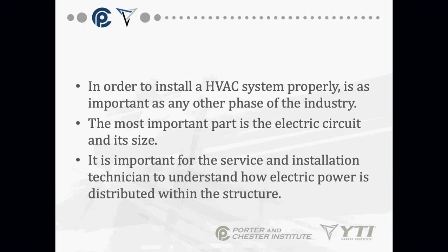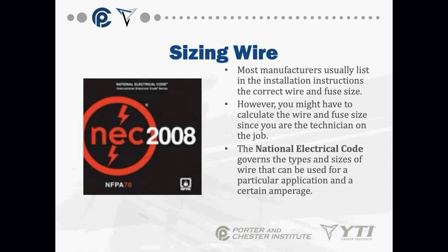The electrical circuit and the size is one of the most important things you have to be concerned about. It's important for the service installation technician to understand how electrical power is distributed within a structure. Wire sizing you can't avoid. It's going to play a part in some of the service calls you are on. Most manufacturers usually list the correct wire and fuse size in the installation instructions. However, you may need to calculate wire and fuse size if you're a technician on the job.